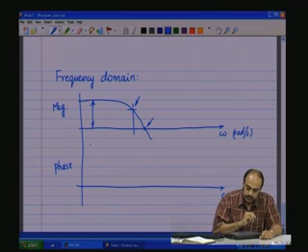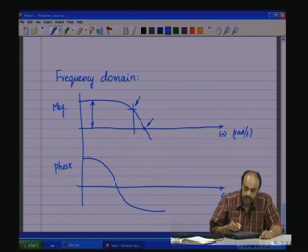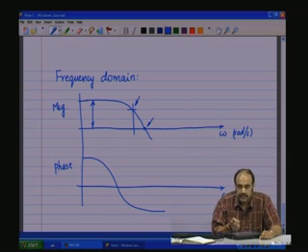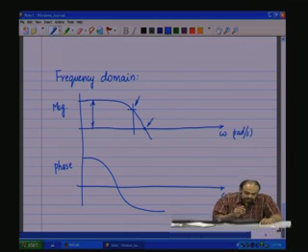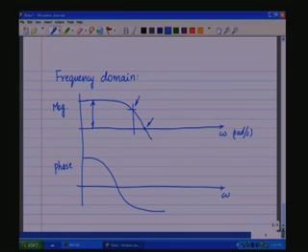So, corresponding to those frequencies, what will be the phase plot and how does it look at various frequencies? Is it going to be in phase, having no phase shift with respect to the input waveform? Is the response having a 90 degree phase shift, or a 180 degree phase shift with respect to the input waveform? These are issues that you can obtain. This is the information that you can obtain from the frequency domain plots.